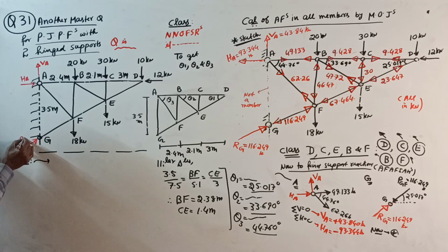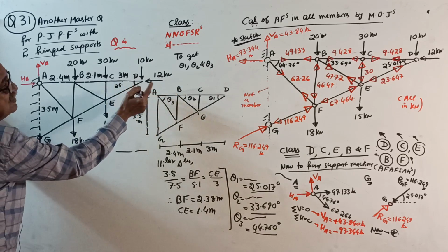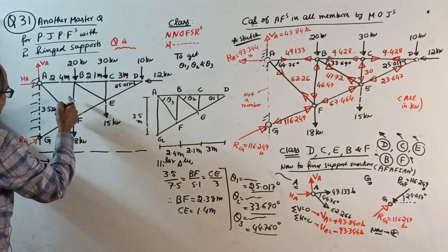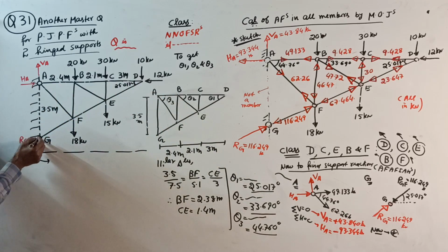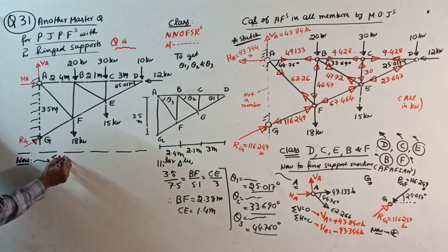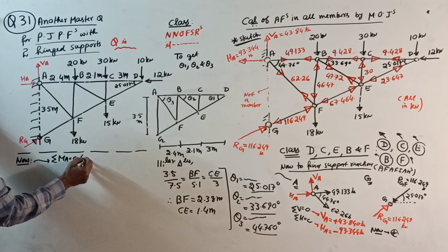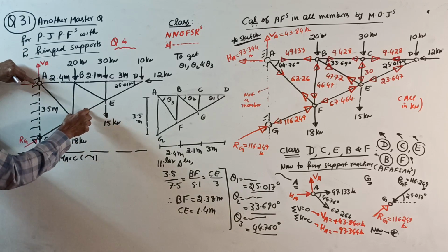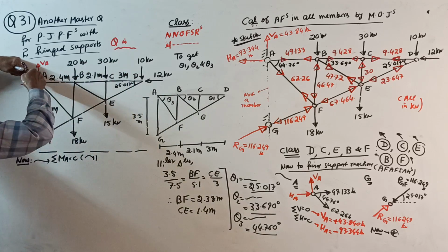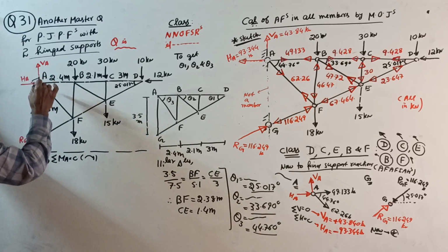That is RG. Now enter this angle, 25.017 degrees. The other is not required. This reaction is collinear, same angle. Now consider sigma M about A equal to 0. I told you to take moment about the point where unknowns are more. Clockwise positive. Be careful, this is an inclined member, so RG into the perpendicular distance. Then you require the perpendicular from A to this line.